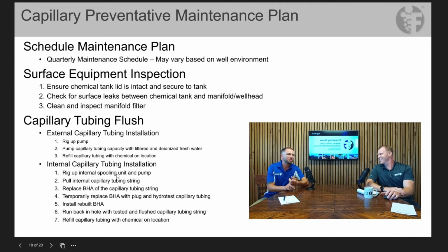Especially out in West Texas. We love wind out there, and it's dusty, and there's nothing to cut it. So making sure lids are on, and that we're always keeping the tanks somewhat full. Because when we fill them, you stir up all the debris, everything. Usually plugged strings happen right after somebody just pumped or just filled up the tank with chemical. Oh yeah, that's very typical.